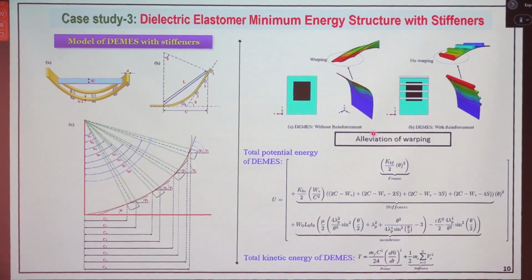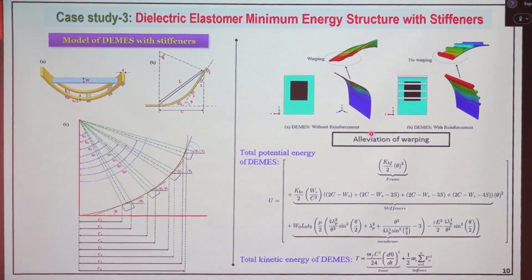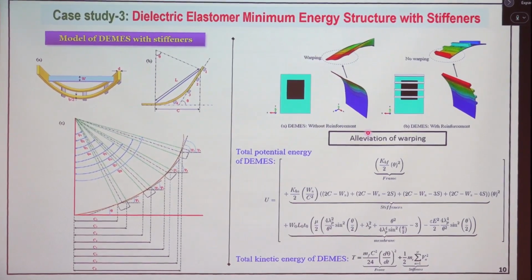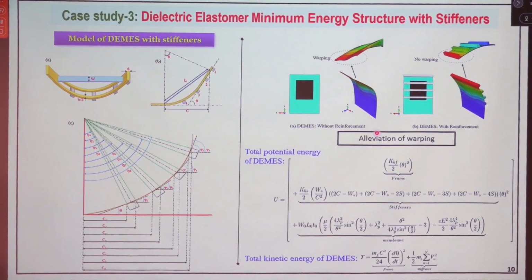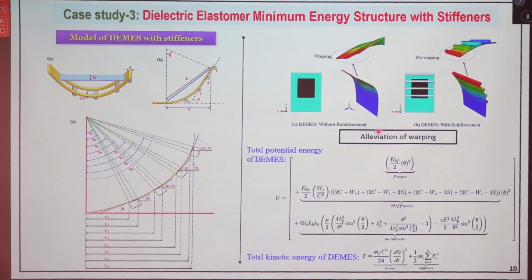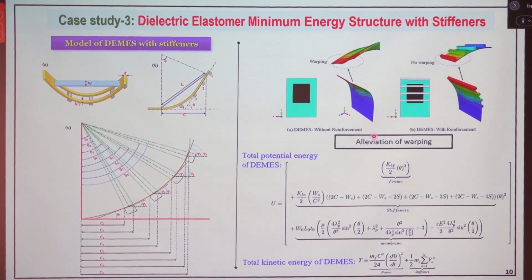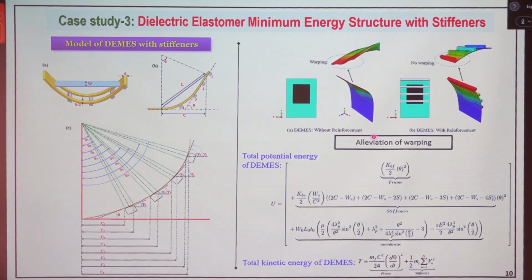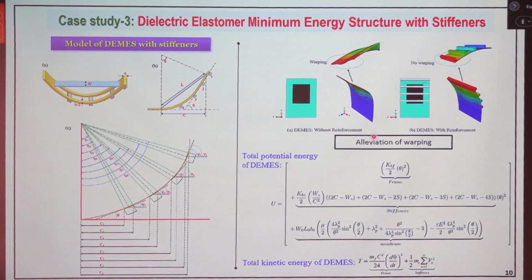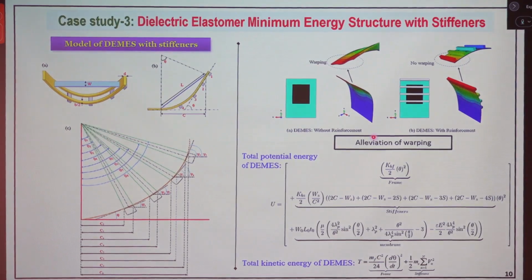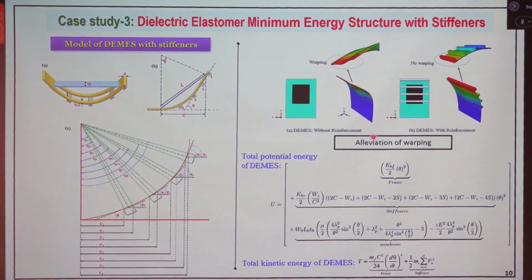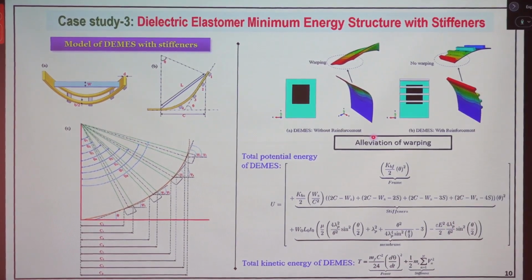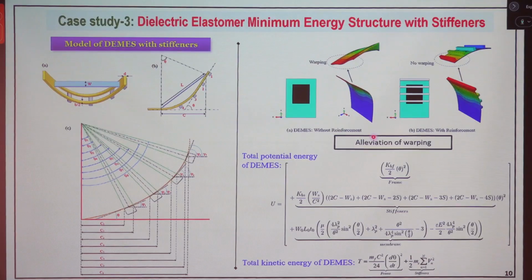Now I say that instead of getting only bending actuation modes, I need twisting actuation modes also. Because in a flapping wing, it is not the case that you will have only bending. You will have bending as well as twisting. So now you know that you need twisting modes also. What you can do is provide the stiffener over the frame at a certain orientation. So now you are seeing how we are governing and pre-anticipating all this. We anticipated that we need a bending actuator, so we cut the shape of the frame in the form of a rectangular bending frame.